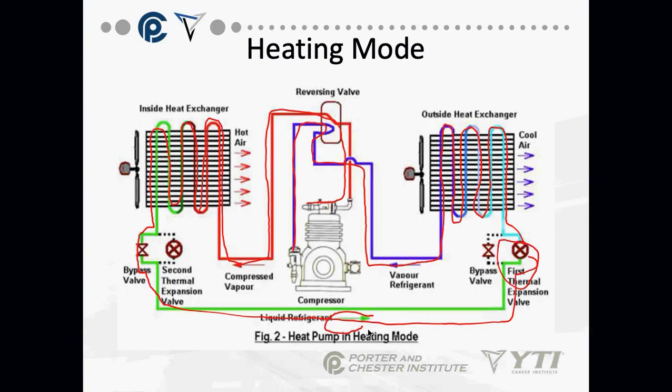Can those reversing valves be put in wrong? Like backwards? Oh, absolutely. There's a lot of people who, when they have to replace a reversing valve, mess it up and put it in backwards. And if you ever have to change one out, just be very sure you don't put it in backwards, because there will be a whole lot of cursing and swearing going on.